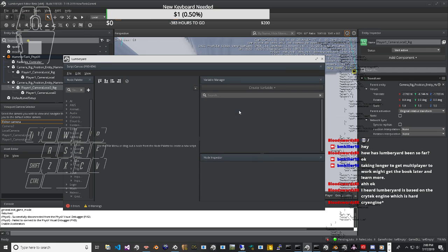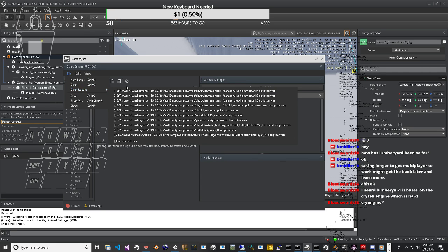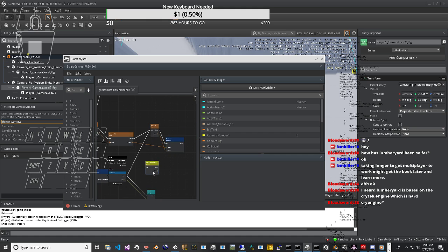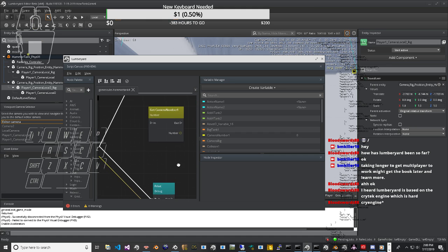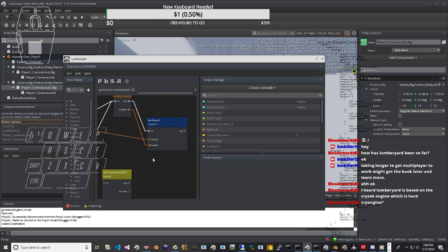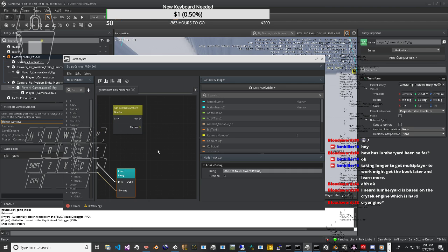The depth axis measures vertical load on the contact patch, in kilonewtons. We can see that these tires have a peak at about 4 degrees of slip and that cornering force goes down as slip goes up on either side of the peak. On the high side of the peak, we have dynamic understeer, where turning the wheel more makes the situation worse. This is a form of instability in the control system of car and driver.